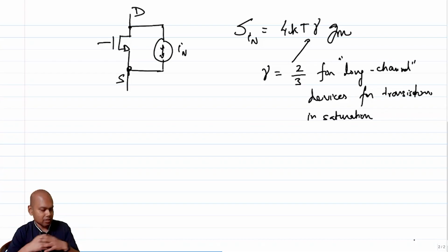If by chance the noise is more than the signal, you will have to design your device in such a way that the noise is lower than the signal that you expect. Which naturally means that for analysis purposes, if we can use small signal approximations for signal, we should be able to use small signal approximation for noise, right?